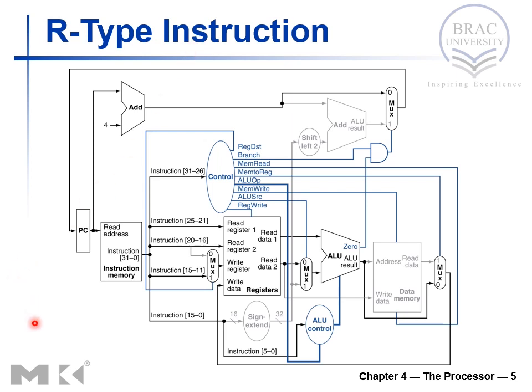For executing R-type instruction, we need selection of 3 registers inside the register file. So this is going to select the source 1, this is going to select the source 2, and this one will select the destination. See, this is register destination. This one will be enabled. So port 1 will be enabled in case of R-type instruction. So this one will be enabled for selecting the destination.